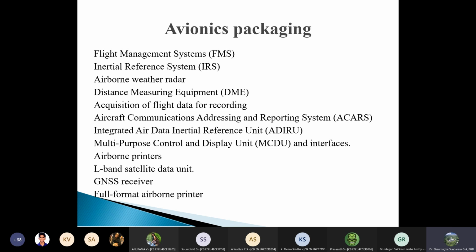So with that understanding, if you can now orient your XYZ axis with reference to those stars, and not any star, but very carefully selected groups of stars, you can certainly consider this as a precise referencing scheme or a coordinate reference scheme against which the actual changes in the aircrafts can now be determined exactly. So if there is a change by a certain pitch or a yaw or a roll by so many degrees, it can effectively be understood in a better manner. So that's the idea of the inertial reference system.